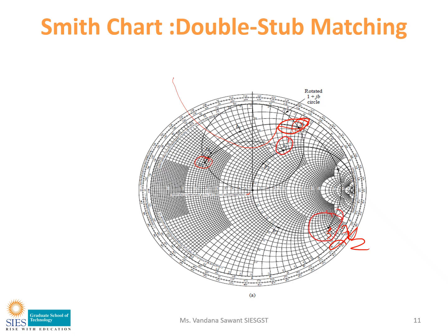We take the radius center to y1 dash in the compass and draw the circle passing through y1 dash, and that will intersect the R is equal to 1 circle at this point, which is called the y2 dash point. Y1 is shifted to y2, and y1 dash is shifted to y2 dash.